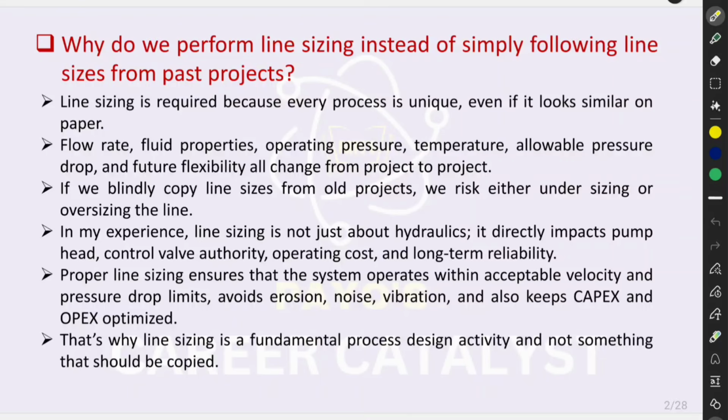In my experience, line sizing is not just about hydraulics. It directly impacts pump head, control valve authority, operating cost, and long term reliability. Proper line sizing ensures that the system operates within acceptable velocity and pressure drop limits, avoids erosion, noise, vibration, and also keeps capex and opex optimized. That's why line sizing is a fundamental process design activity and not something that should be copied.